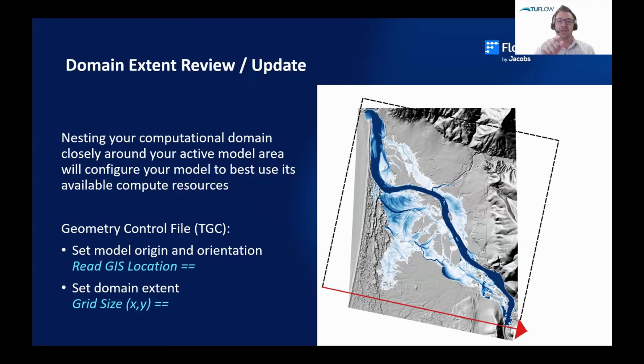That one change reduced my simulation time from 57 minutes to 38. So it's a pretty significant reduction in simulation time. That should be your first step whenever you're building a model. Think about your computational domain.